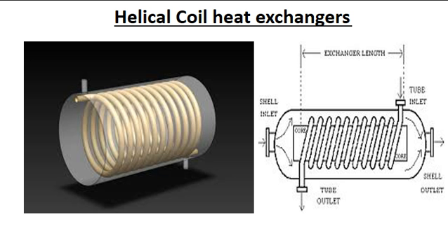Now we will discuss helical coil heat exchangers. These are gaining wide importance nowadays because they can give a high heat transfer coefficient in a small footprint of surface area. This design is that of a condenser and is usually mounted vertically. It is designed to cater for the subcooling of both condensate and non-condensables. The coolant moves in a spiral and leaves via the top. Hot gases that enter leave as condensate via the bottom outlet.